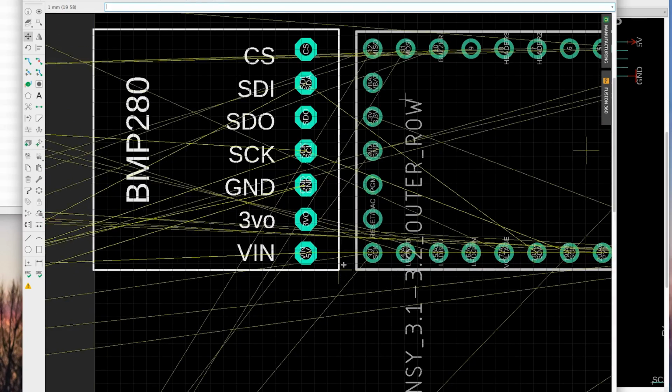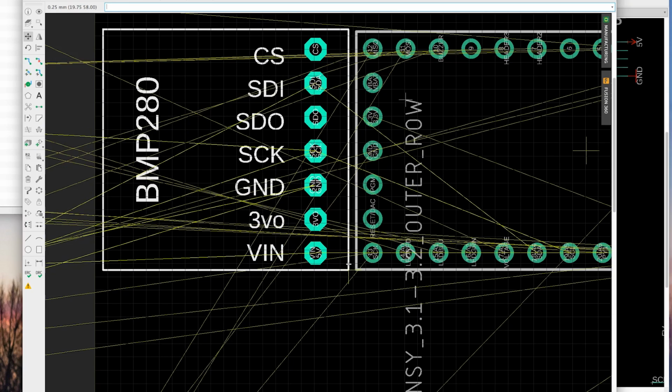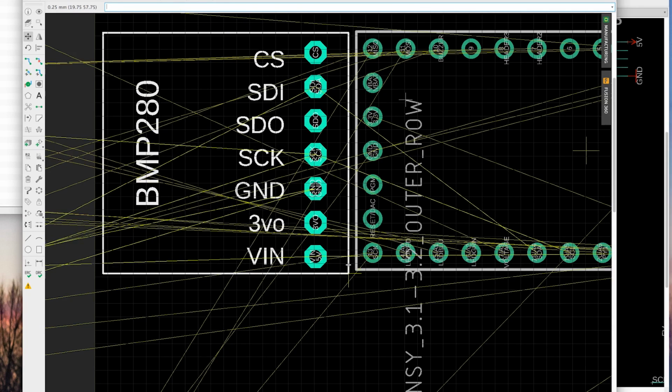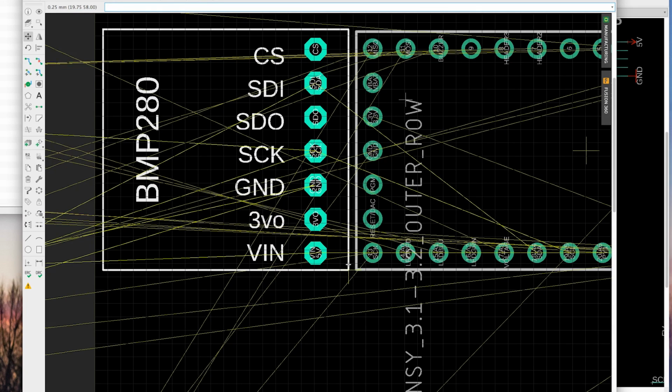Once again, I'm going to move it in. And if I hit the Option key or the Alt key, I can get finer precision in where this device goes. So I'm going to move it up, kind of near the Teensy. I'll leave a little bit of space here, and then I'll click, and now it is mounted there. Of course, if we're not happy with any of these placements, we can move them around after, we can change things. It's all pretty flexible, especially in the beginning phase.